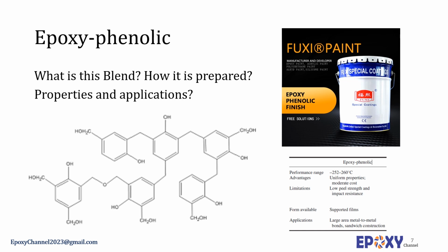Epoxy phenolic adhesives are made by blending epoxy resins with phenolic resins to improve the high temperature capabilities of the standard epoxy resins. These adhesives are generally based on blends of solid epoxy resins with Resol-type phenolic resins. The epoxy resin component is often not the predominant component in the blend, depending on the end properties required. They are commonly used for bonding glass, ceramics, and phenolic composites. Because of their relatively good flow properties, epoxy phenolics are also used for bonding honeycomb sandwich composites.